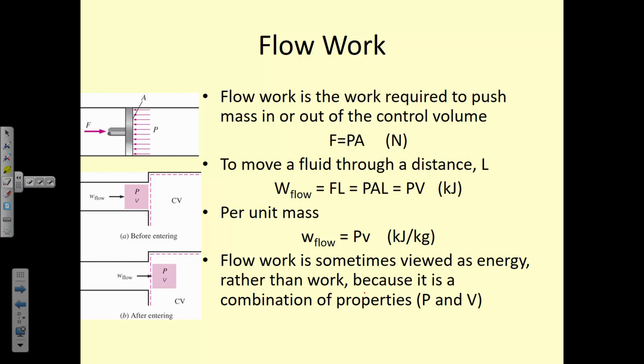Okay, so flow work, we talked a little bit about this. It's very similar to boundary work in that it's the work required to move this piece of fluid into the control volume and then out again. So when we're talking about flow work, it's the same term, it's PV, and it's accounted for in our energy balance because we've already combined it with internal energy. So U plus PV is equal to, I should do this with the pen, enthalpy. Okay, so when we look at our energy balance for an open system, we've already done this calculation, and instead of having internal energy on the right side of the equation, we have enthalpy.